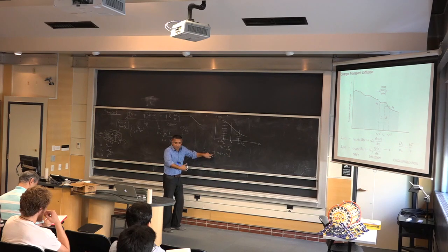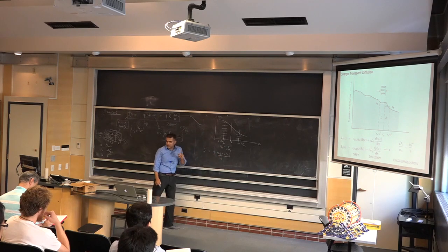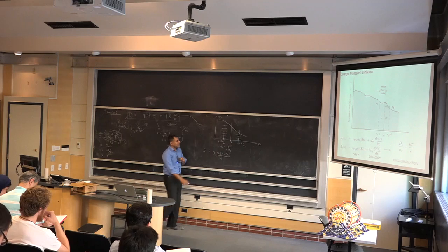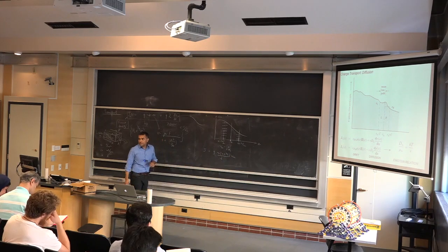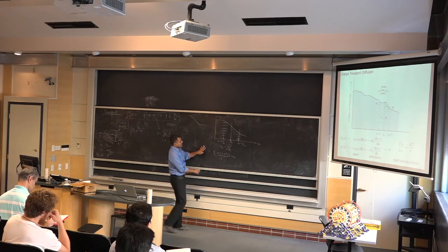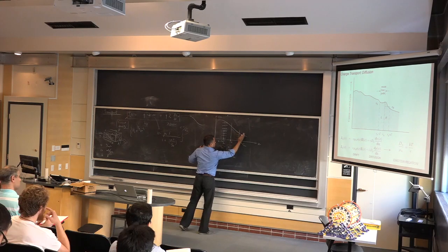But the number of electrons that are moving to the right is half of that, not all. So half of them are moving to the right, times the velocity, which is the thermal velocity. That's what you said. Does that make sense? So that's the number of electrons. This is not the total current. This is just the current of the carriers going to the right here.